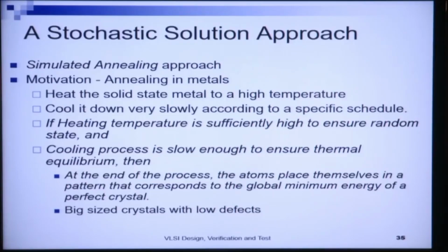And then if the cooling is slow enough to ensure a thermal equilibrium, then at the end of the process, the atoms place themselves in a pattern that corresponds to the global minimum energy of a perfect crystal, and with this we obtain large size crystals with low defects.